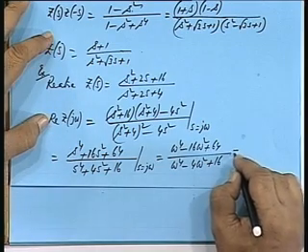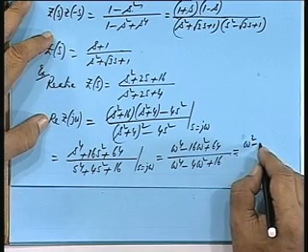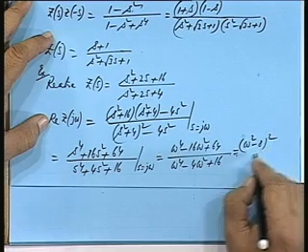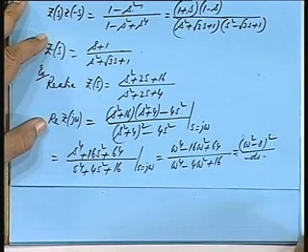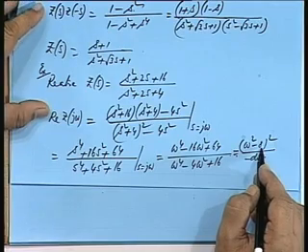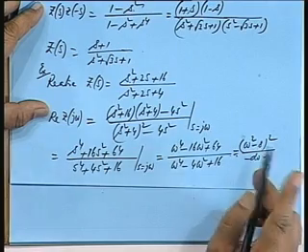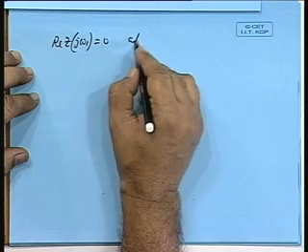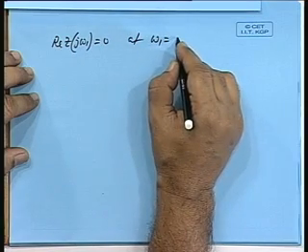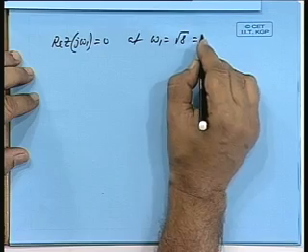Now this you can see is (omega squared minus 8) whole squared. So this function becomes 0 at omega squared equal to 8. We have to first of all track that frequency at which the real part vanishes, is it not? So the real part of Z(j omega 1) equals 0 at omega 1 equal to root 8, that is 2 root 2.